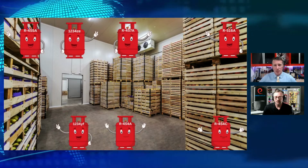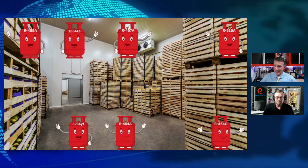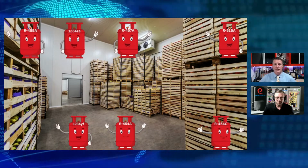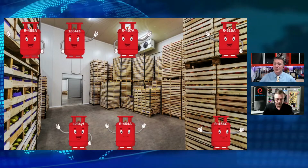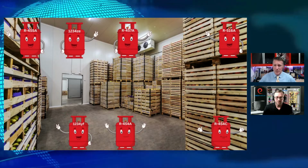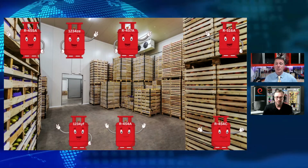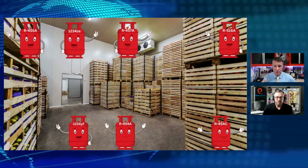So when we talk about cold storage, we are typically talking about 404 style systems. We might have a 134 out there. I've seen some 134A refrigeration walk-ins, but a lot of times we're going to be working with R404 in these systems. So the replacements that we're going to see, since a lot of these are a lower temperature application, we're not seeing R32, right? R32 is our medium temperature, high pressure refrigerant. We're probably not going to be seeing that one. If it is, it's going to be an update down the road. So our R32 has not met this list, at least for our SNAP 26 proposal.